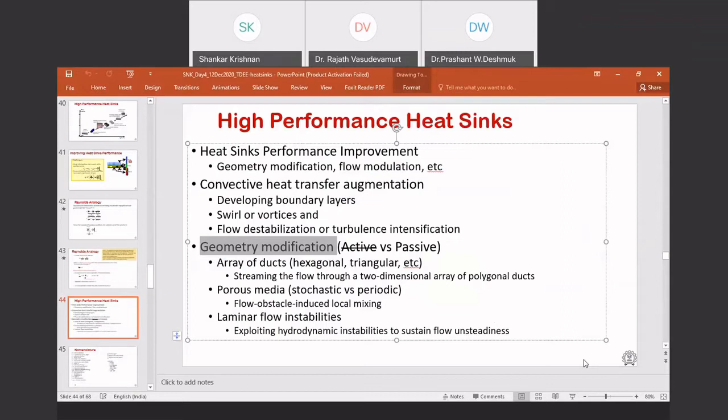However, what we mean here is the class of porous materials like open cell metal foams, I'll show some pictures later, or periodic foams that we work on in our lab here at IIT Bombay, where the metal ligaments, the construct of the porous material, are continuous and it has a three-dimensional pore shape. The pore, meaning the area through which the flow happens, is also continuous.